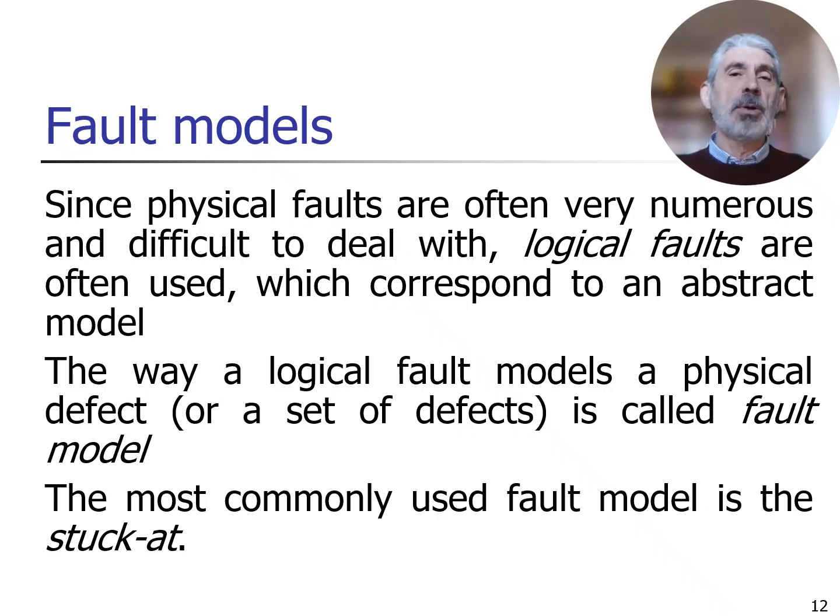So we need a more practical approach. And the practical approach is based on introducing what are called fault models. A fault model is a representation of possible defects, which is hopefully easier to manage, so that we can more easily generate the test stimuli which are used during test, and we can more effectively perform the test.